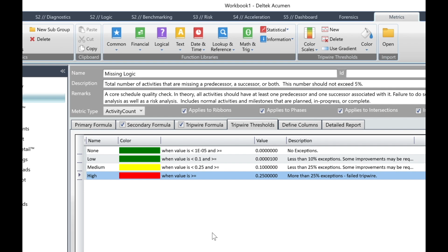Now let's look at colors and boundaries. We have criteria descriptions and values to the right of all the colors. Each description will provide a value range for each color. Now the colors have 2 modes, discrete or gradient. In the discrete mode, colors are not blended and change from one color to another once the next limit is reached. In the gradient mode, you'll be able to see if results are trending close to a threshold as the colors blend together. You can toggle between discrete and gradient modes by selecting the gradient button. So, you can specify discrete or gradient boundaries between the colors.